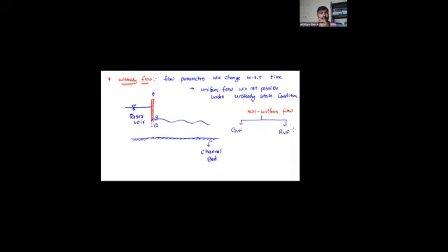So wherever you see the wave pattern, whenever you see the wave pattern in the flow, that is unsteady flow. And if that wave pattern is gradual, then we are going to call it a gradually varied flow. Example, flood waves in rivers. We call it an unsteady non-uniform gradually varied flow.